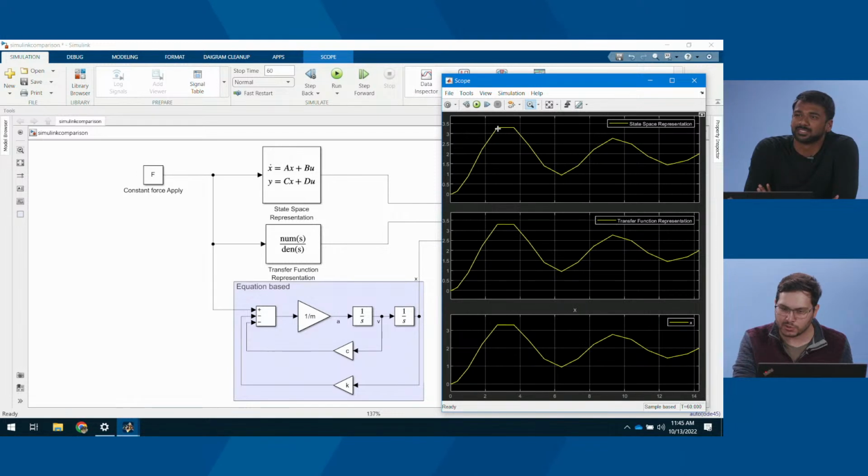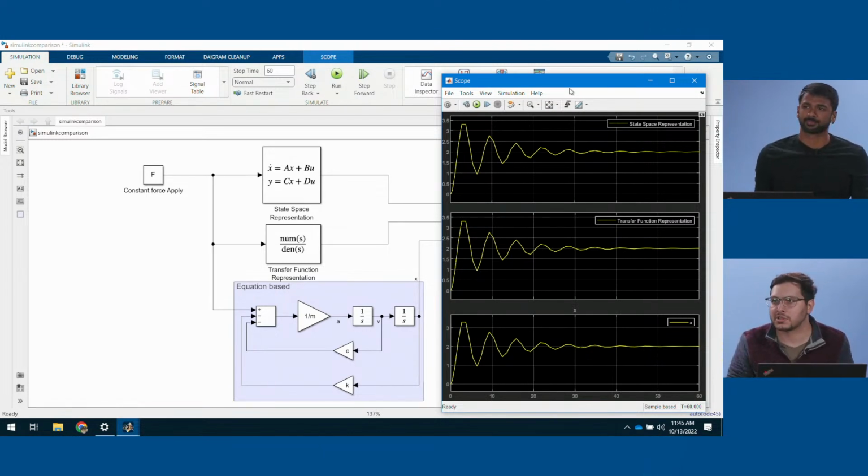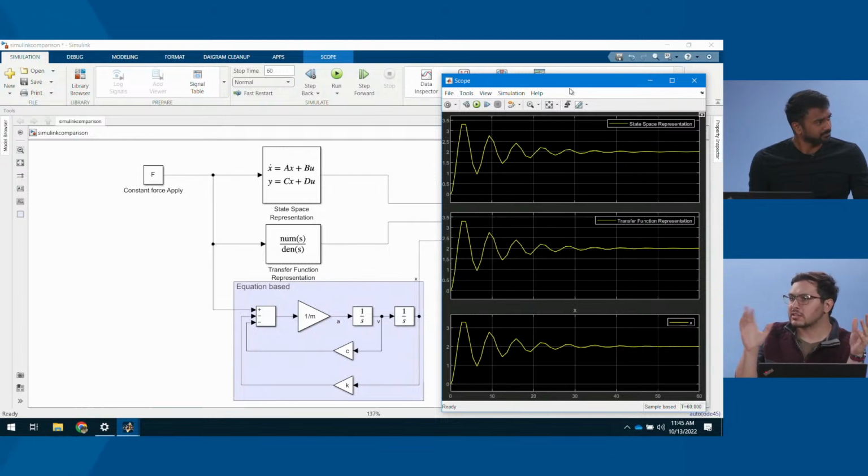I don't think, for that half a second, my mass spring damper was standing still for a second, right? Yeah, it seems unlikely. So what this is, is the Simulink Solver, because I've got all these blocks, and what's happening is Simulink is trying to solve the system of equations that represents all of these blocks. The way I have it set up now, I'm letting Simulink decide what step size it should take. So like how often it should make those calculations, essentially.